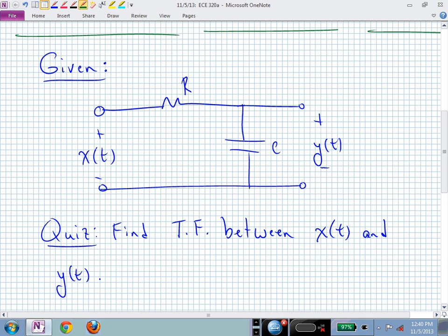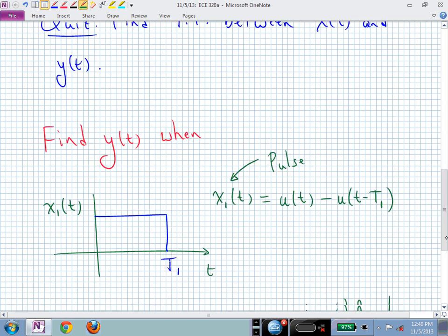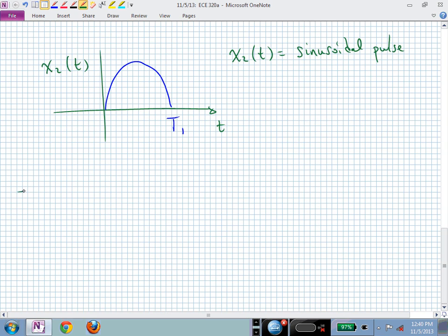You probably go into the frequency domain. You say, give me the S domain equivalent circuit. And what do we need to do with the initial conditions? We don't worry about them if we're working with the transfer function. So now we can start to look at the transfer function of that particular circuit.